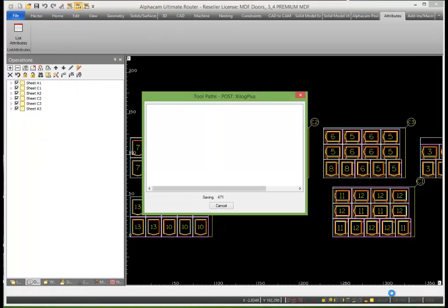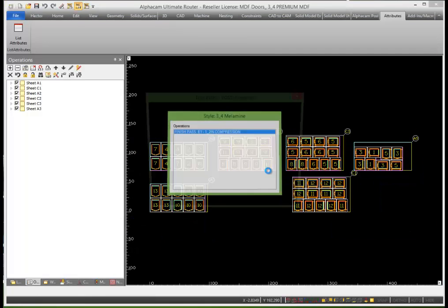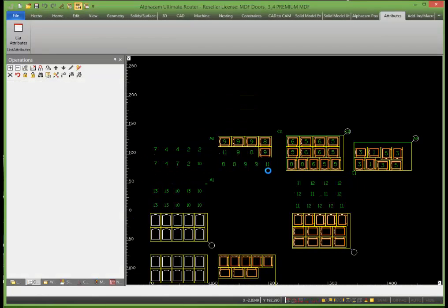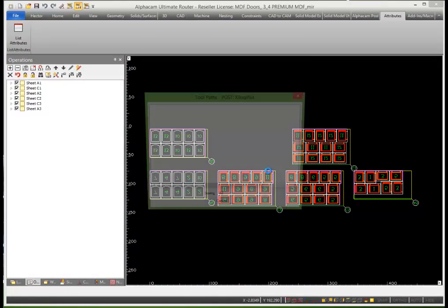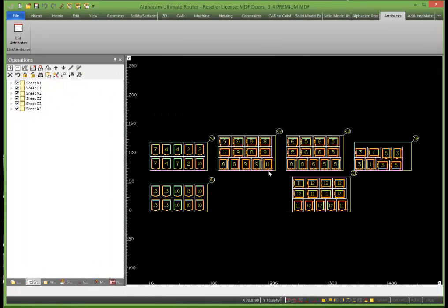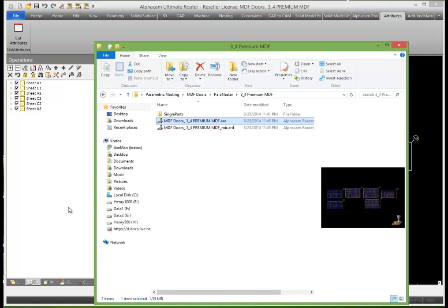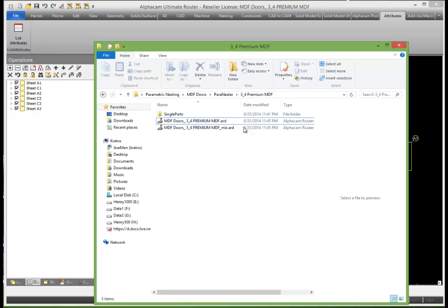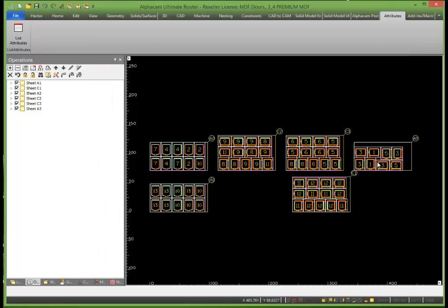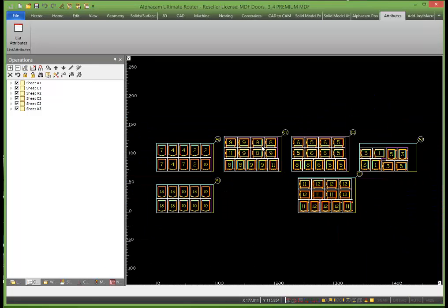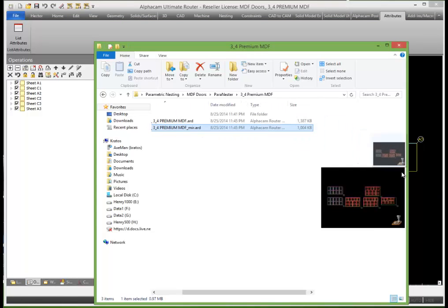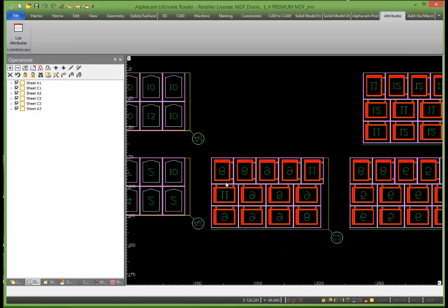So now immediately after the generation of the G-code for the top side, you will see that we do the reverse side nesting. This is when the software is going to completely generate a mirror of the part, add the backside operations, and generate the code. If we quickly take a look at what are the results that we got out of the software, you'll see that of course we have all of the drawings for the top face, which is what we've got here. We also have all of the drawings for the mirrored side, which we have here.